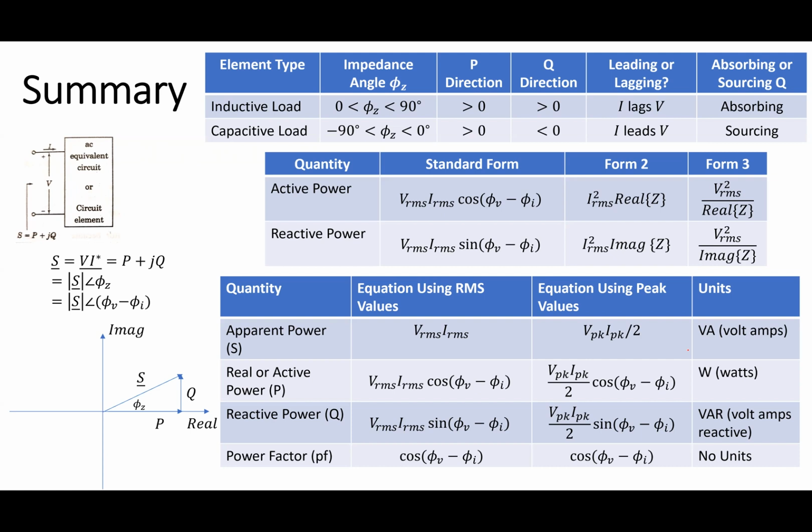That way, if I had a pure resistor, and I wanted to calculate the power in a pure resistor, it's still V times I, just like it is in a DC circuit. So sometimes we call the RMS value the effective DC value of that sinusoid, because it allows us to compute power for a resistor by just still doing V times I. That's the whole reason why we do it. It turns out to be simpler to do the math that way. That's all.